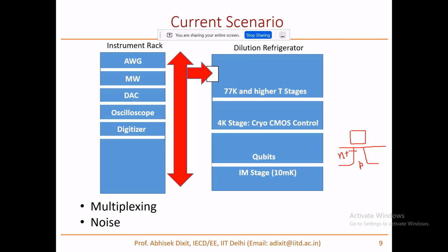So when do these electrons enter the channel? All of you who have followed the basic MOSFET physics will know that electrons cannot enter the channel unless the barrier for electron injection is lowered. And how does this barrier look? The barrier looks something like this. So your electrons in the source are here. They cannot climb this barrier.